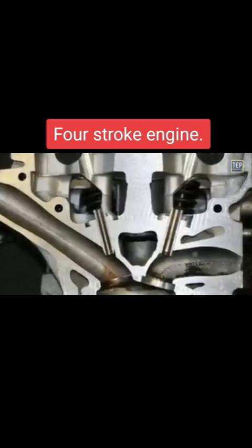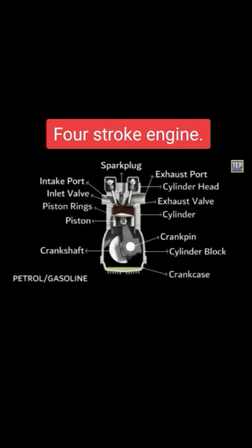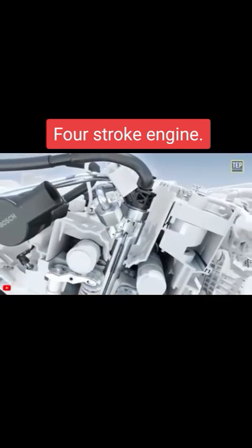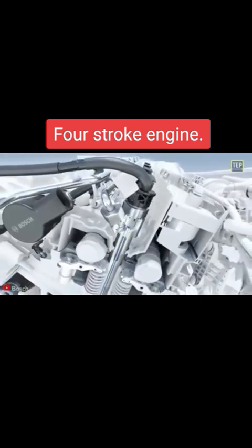For a petrol engine, a spark plug is used to ignite the compressed air-fuel mixture. For a diesel engine, an injector is usually used in the compression ignition engine. It sprays the fuel into the combustion chamber at the end of the compression stroke. It is fitted on the cylinder head.